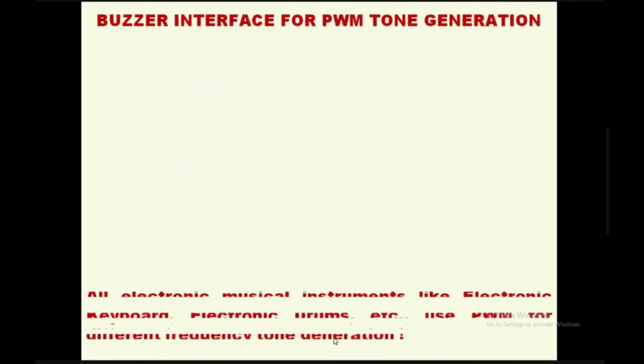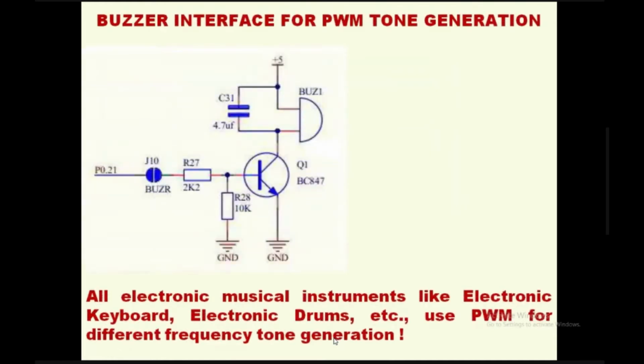Now, the buzzer interface. The kit we are using to experiment with the LPC2148 microcontroller is the Labs kit. In this Labs kit development board, there is a buzzer which is connected to GPIO pin P0.21 of the LPC2148 microcontroller.